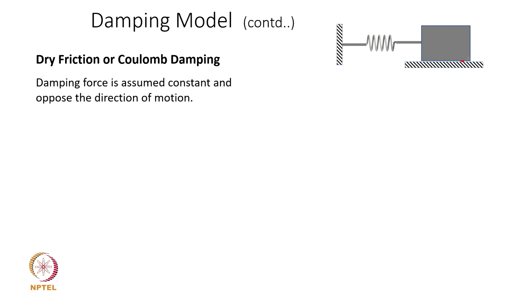There is no explicit dashpot here, but if this spring mass system, the mass is resting on a stationary surface, as you see here, and then when the mass oscillates and travels back and forth, the friction between the moving mass and the stationary surface generates a force at the interface, which we all know is given by mu into N. In this particular case the weight of the mass is acting on the stationary surface, and therefore, N is actually equal to m into g.